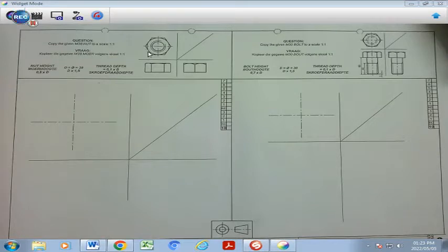That refers to this slanted face here, and that refers to that slanted face there, and that flat part there is this bigger face that you see here. If you project this over onto your 45-degree line and you project it down, you will find that 2 faces will now be drawn here as a result of the 2 faces that you will see on this side there.